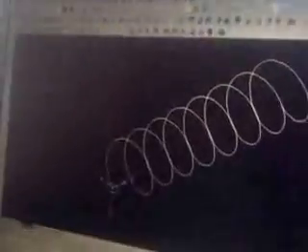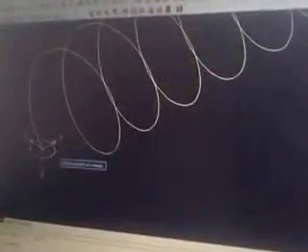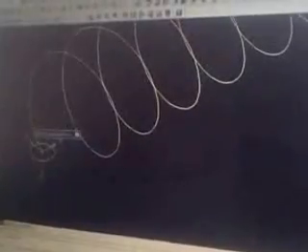Then I go to the modeling tools, we have all here. There you have loft. No, I don't need loft. I need revolve or I need sweep. I click on sweep. If you go to the command line, this is select object to sweep. I select this circle to sweep. Then this part to sweep around is this part. I click on it.